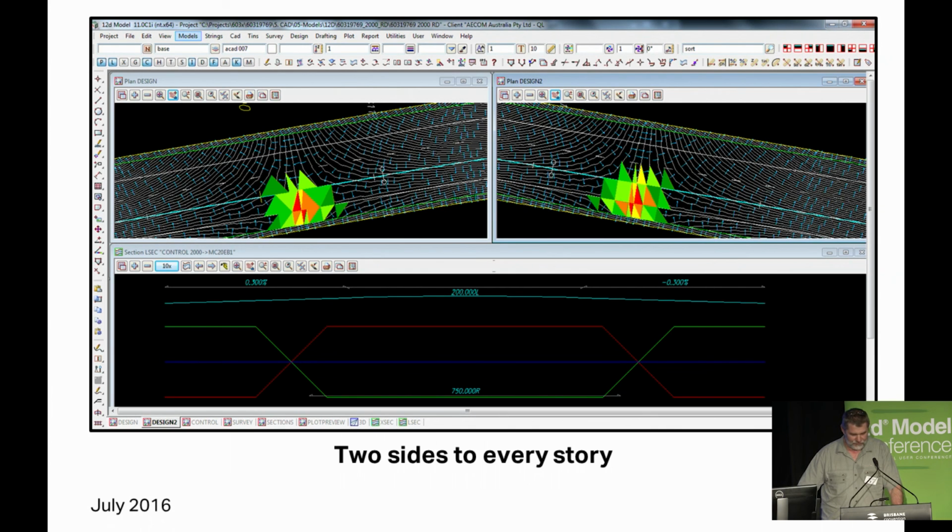This means if your control line is placed inside the road lanes, you're always going to need a longitudinal grade of between 2 and 3% through your superelevation transition areas. And in flat topography, this usually isn't practical, particularly in brownfield or overlay projects like highway upgrades, where these induced grades result in vast areas of thick overlay, which are near impossible to construct and uneconomical.